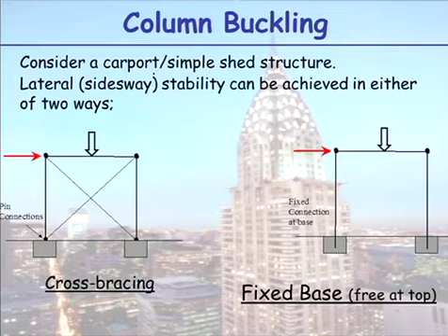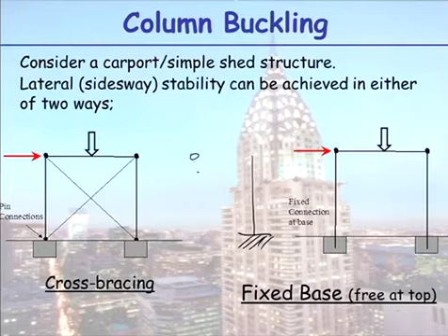Where you can't put that bracing in, you effectively have to create that flagpole condition. So in this situation here, I've got a flagpole. Over here, I say I have a pin-pin column situation, because this wants to move sideways, and can you see the cable here? It's triangulated.